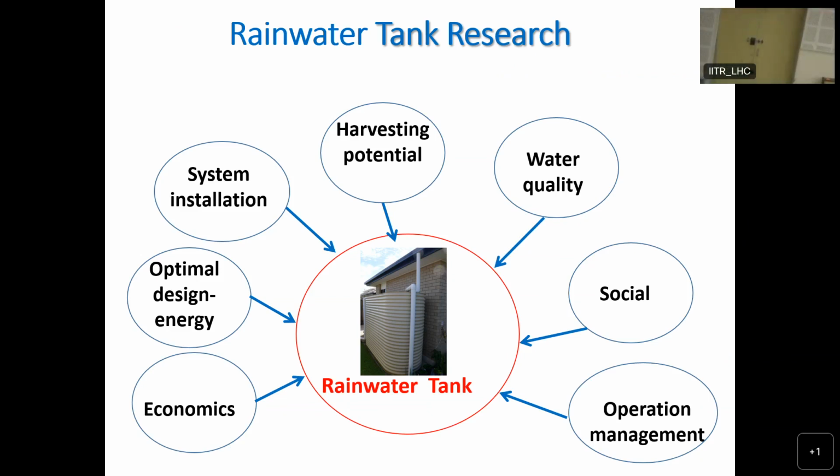So basically, 100 multiplied by, that is meter cube, and then you multiply by a coefficient or a factor, 0.8. Why do we have to multiply that? Because we can't capture 100%. That is 0.8. Again, that will depend upon the configuration of the rainwater tank system. So, the reason for applying this factor